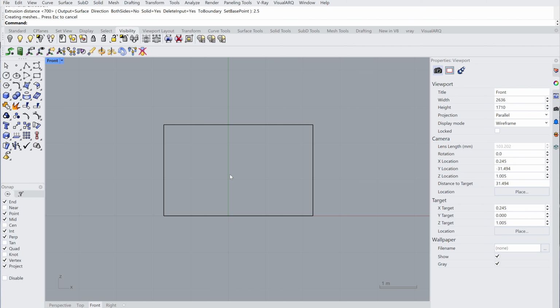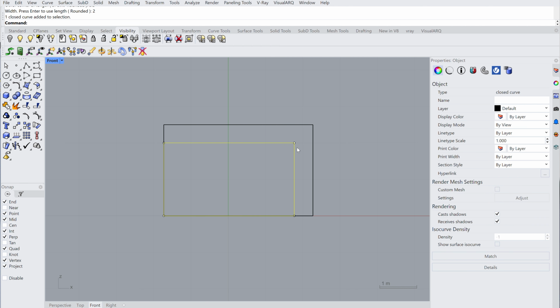Why 7? Again, this brings me back to the code. In Brussels, you need, and this is the minimum requirement, 25% window to floor ratio. So 25% of the 28 square meters we did before, that equates to 7 square meters, if my math is right. Let's do the window, 3.5 meters by 2. Now I'm going to place it in the middle of my wall, okay?